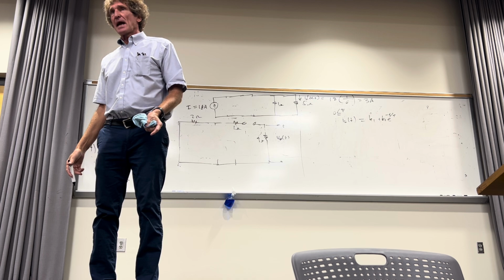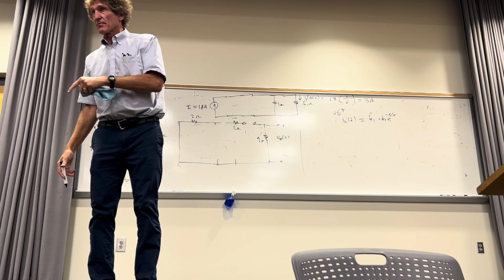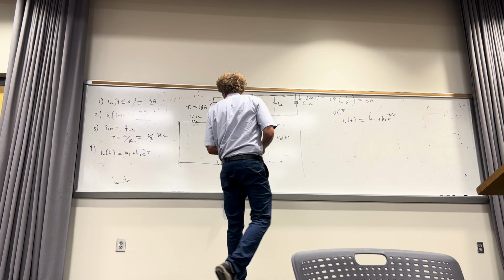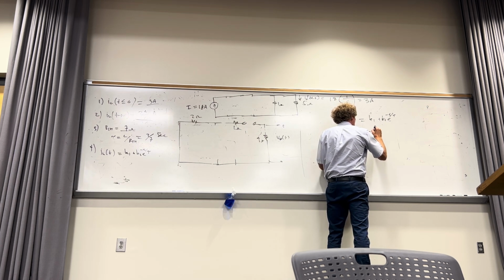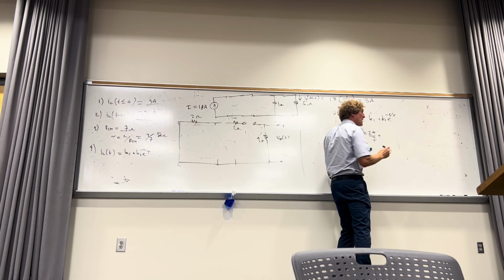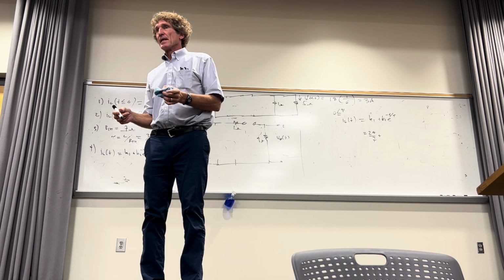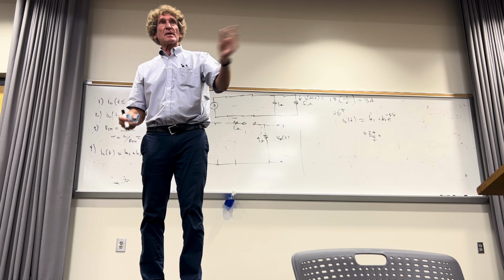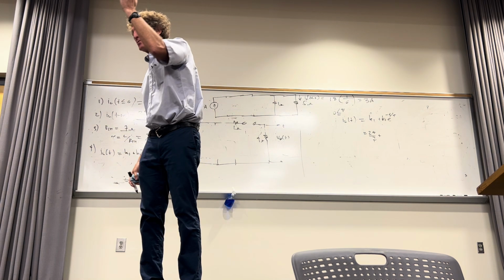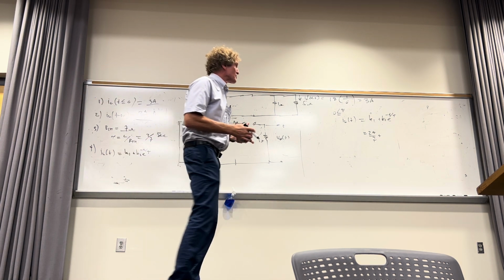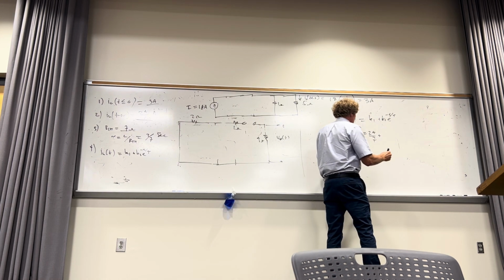Now I replace K1 with the value of the current as t goes to infinity. You understand the reason for it? And that's, what is it, 24 over 7. So now I say this is 24 over 7 plus, I still have K2 e to the minus t over tau, right? But how do I figure out what K2 is, somebody? Evaluate that equation at t equals 0, right? So at t equals 0, e to the minus 0 is 1, right? So I have K2 here.